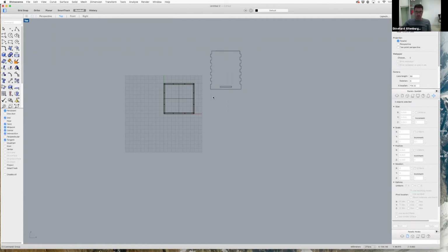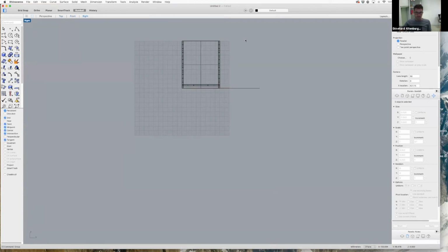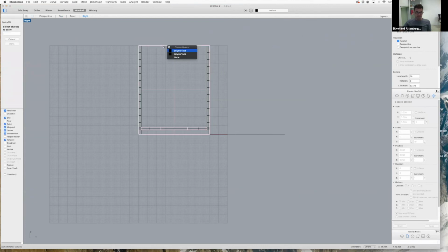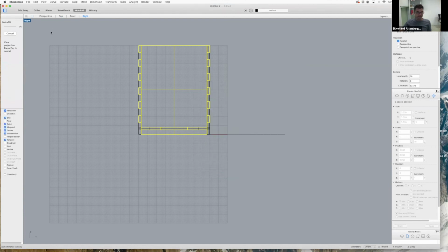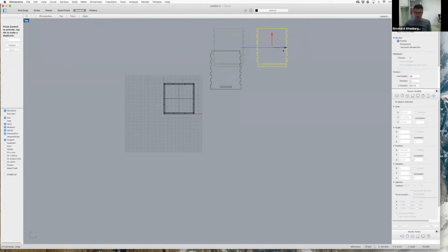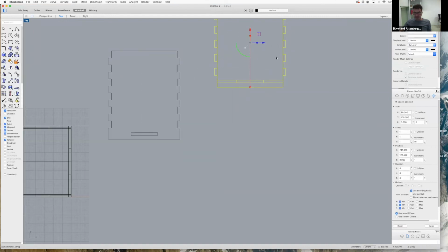So this is one wall. So this is the top and the front. So this is the front view. Now we go to the right view. We do the same. We make 2D. We select the object we want to make in. It must be a polysurface. It's this one here. Let's not group output it. Your projections will always go to the ground view.